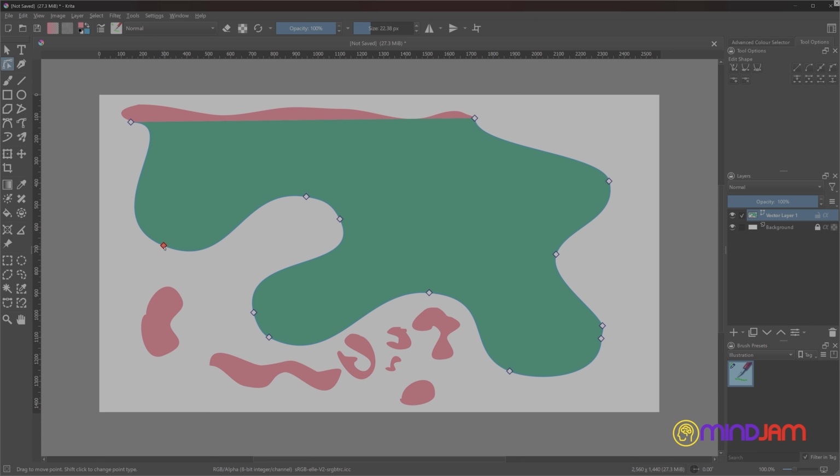A square node represents a symmetric point, where your handles will move with each other to keep symmetry, allowing for an easier use of smooth curves or transitions. A diamond node represents a line node, where only straight lines occur, or a curve node where you can use the separate handles of the node to manipulate the node into creating an imperfect or less smooth curve. A circular node works similarly to the symmetric point, but it makes a perfectly smooth curve.